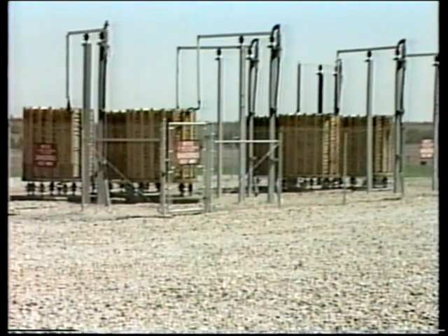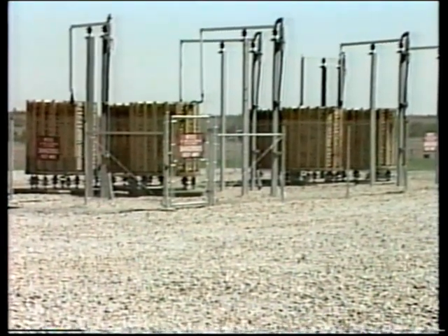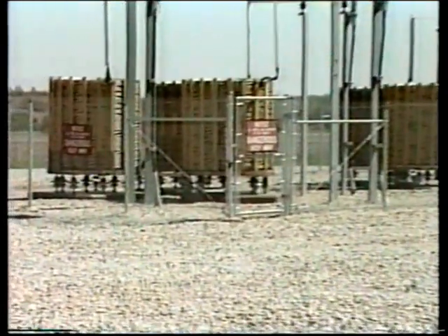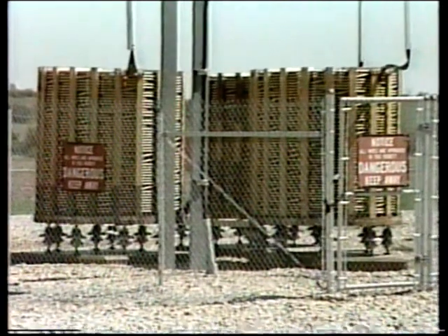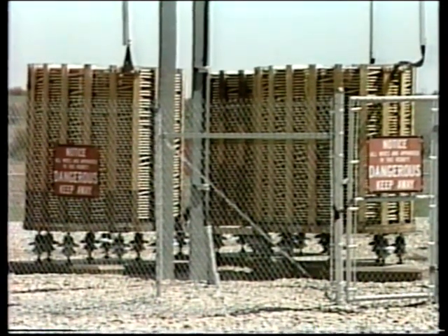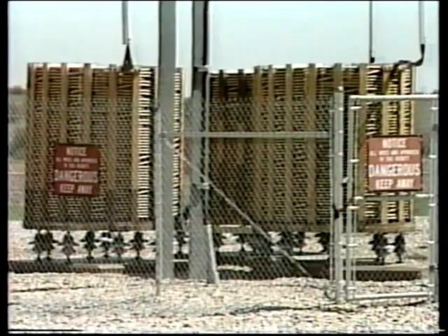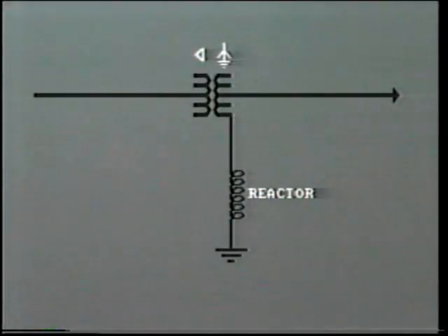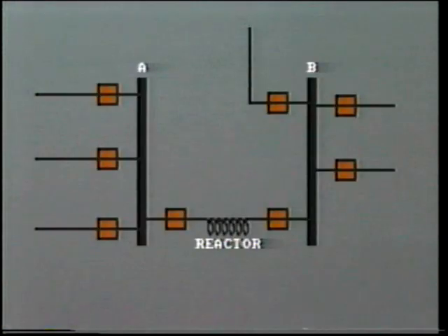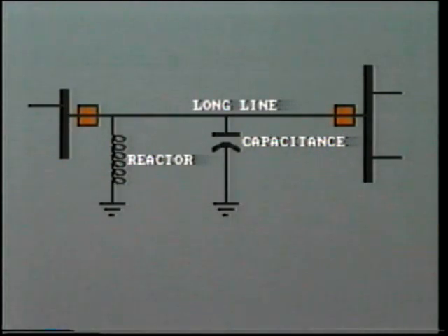Now, at this point, let's extend our overall view of transformer protection to include reactors. This is because there are many similarities in construction, and therefore protection is also similar. Generally, reactors are air-cooled or oil-immersed single or three-phase windings on an iron core. Where is the reactor installed? Well, typically in a grounded neutral to limit fault current, between buses to reduce magnitude of current flow, or shunt-connected between line and ground to compensate for capacitance on long lines and prevent high voltage levels.